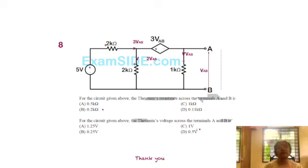Now we need to find out the Norton's current. For that, let's short circuit A and B as shown, and we see that the voltage VAB becomes equal to 0, because the short circuit has a voltage equal to 0 across it. Which means that the dependent voltage source 3 VAB also becomes 0 voltage. So now we have a short circuit across the 1 kilo ohm, and we are also having